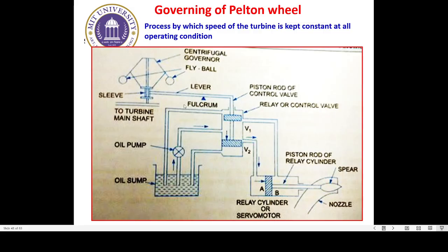I have a number of pipes which connect the oil sump with the control valve, and the control valve with the servo motor, right? And I do have a spear or a needle which is provided toward the nozzle. The spear and its rod get displaced inside the nozzle.